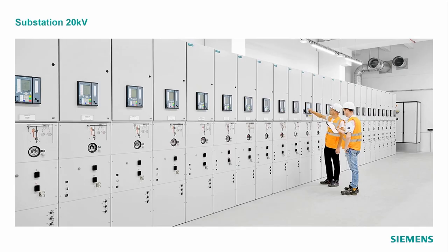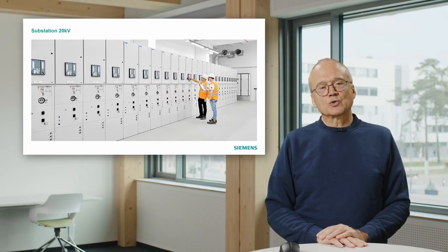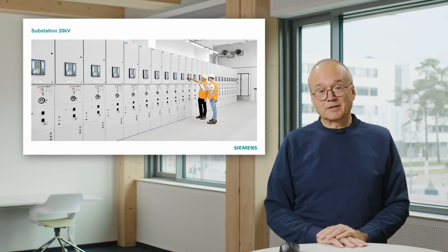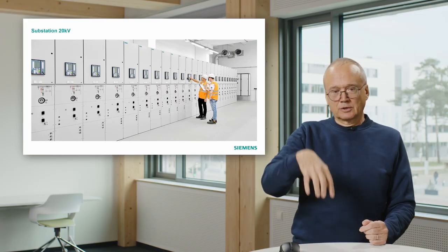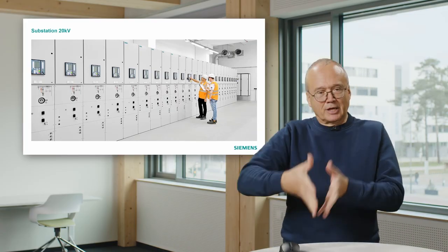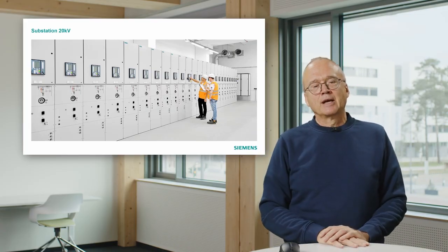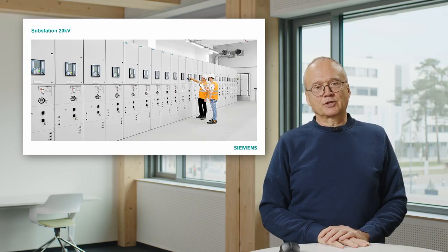In this case, it's an indoor substation. You see here the bus bar goes through this whole installation from left to right. And in every compartment, you see it's a big substation. We have many compartments there. In every compartment, you have 1 circuit breaker. The outgoing feeder goes down to the bottom. That means the cables are underneath. And you also see the protection relay installed there.